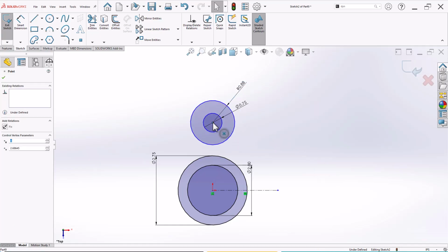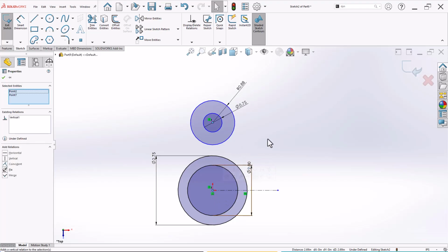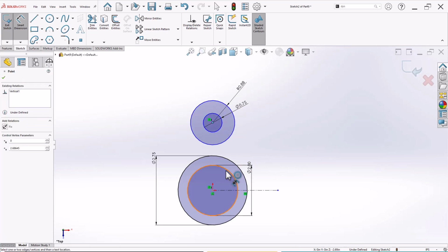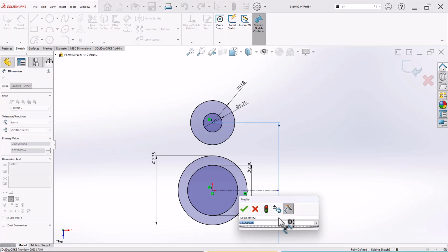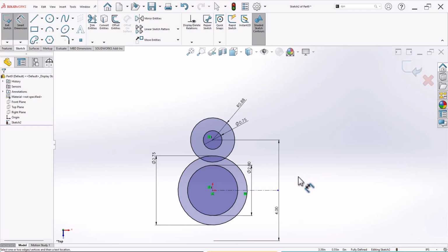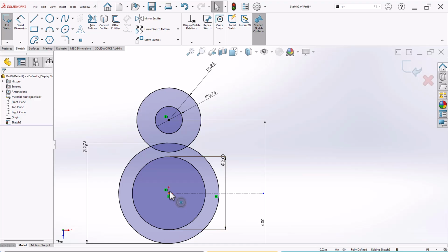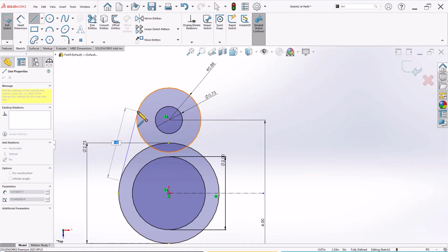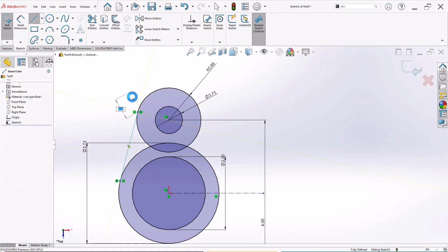Now here these two circles must be vertically aligned. Now I want to give the dimensions. So the center line between them is 4. Select this, and this is 4. Okay. So indirectly it is 2 from this origin to this circle. Now let's add the lines. Now here I am drawing the tangent line. Clear from these coincident and tangent options.